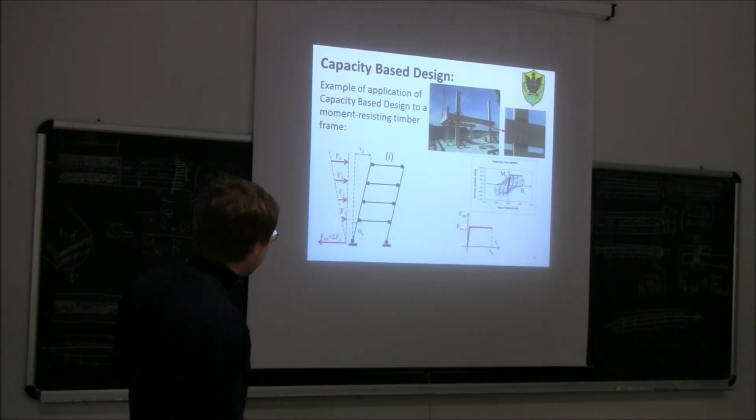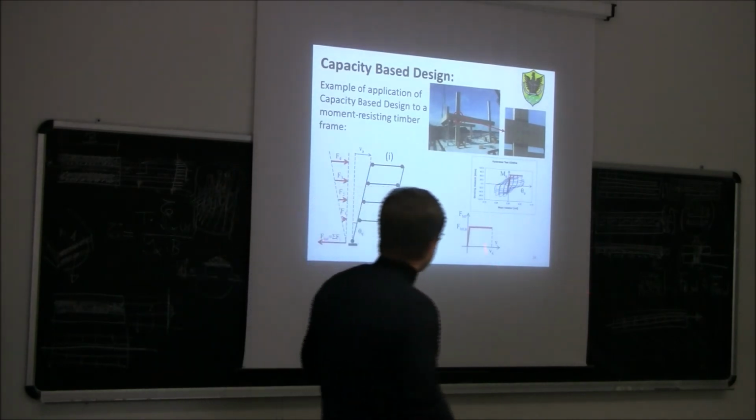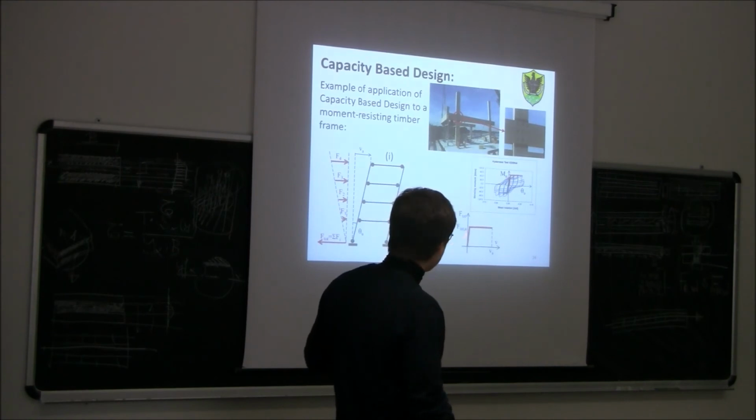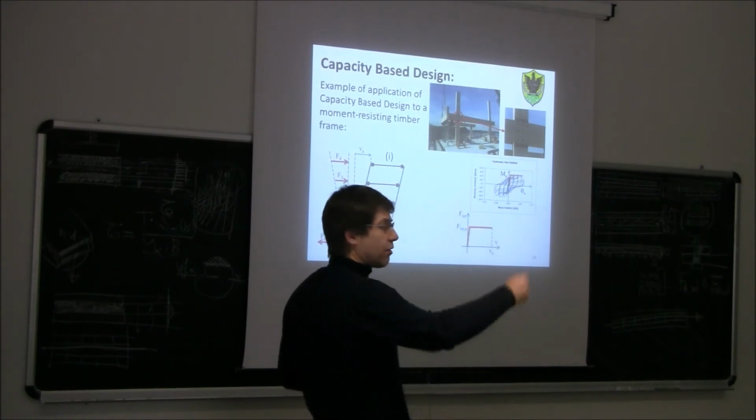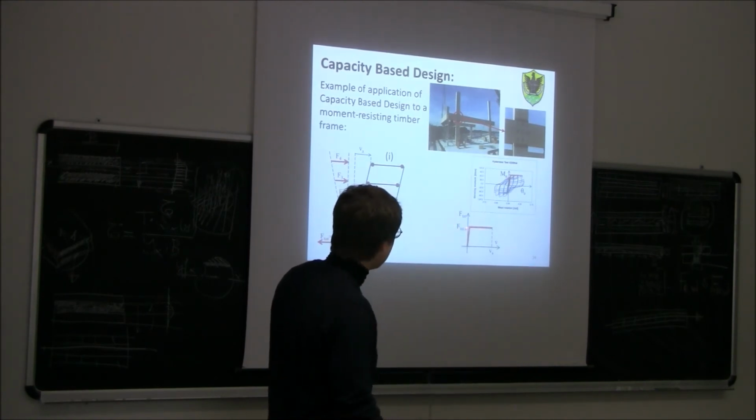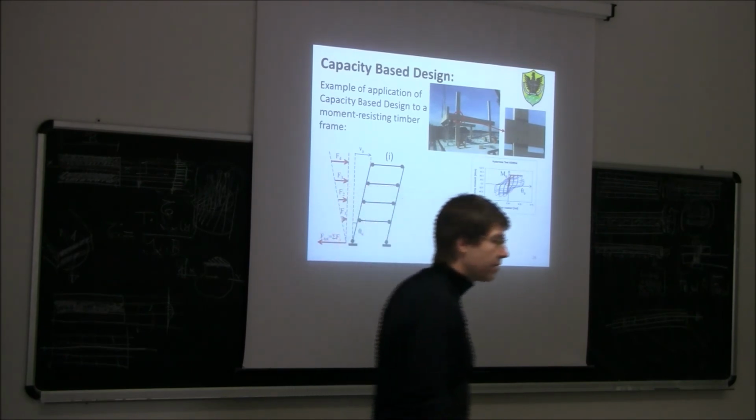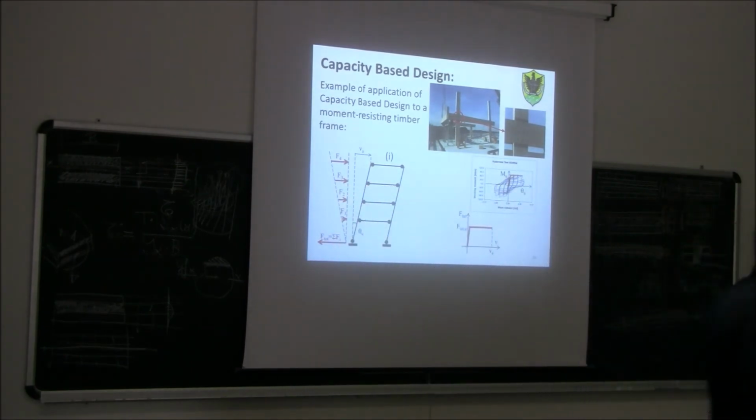Elastic initially, and then when the joints start plasticizing, since the joint has an elastoplastic behavior, we have a simultaneous plasticization of the joints, and we end up, you see, with a global elastoplastic behavior. So in the end, we will have one deflection on top of the building equal to VA.